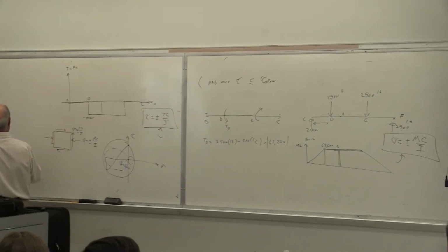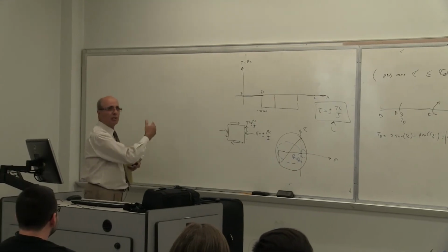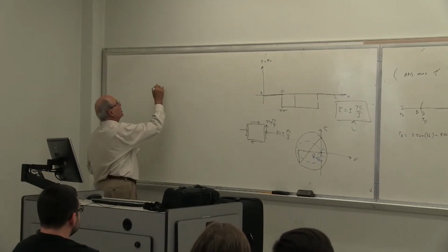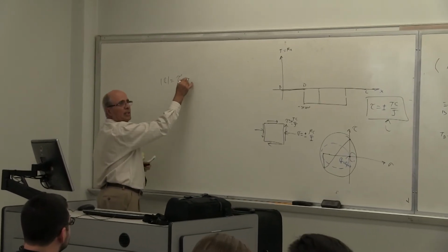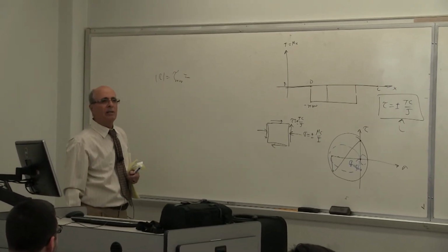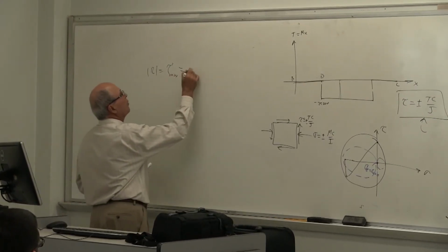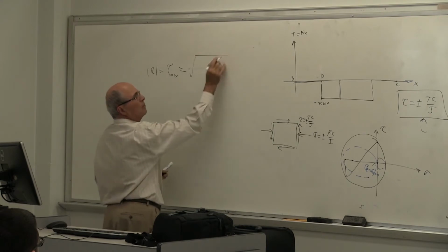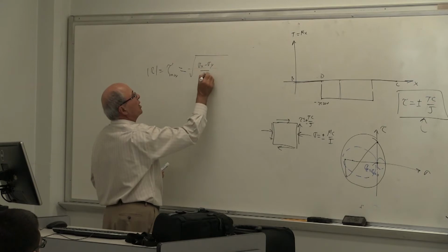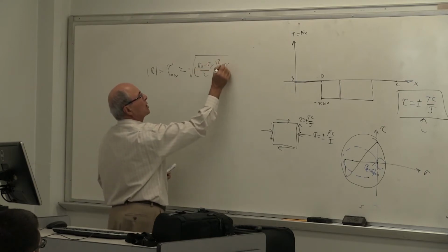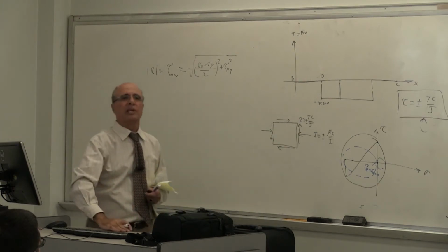So absolute maximum shear, I'm going backward because I'm running out of room. I hope you understand. It's going this way if you want to write it down. So what is R equal to? Tau max. Is that correct or not? Yes? What was the equation of the tau? Everybody should more or less remember, because we always use the circle, but the equation of the tau was square root of what? Sigma x minus sigma y divided by 2 squared plus what? Plus tau xy squared. This is something that you can pick up from the book. Is that correct or not?